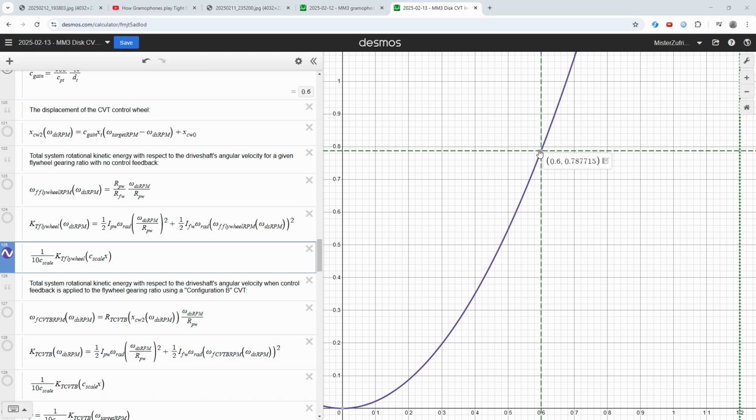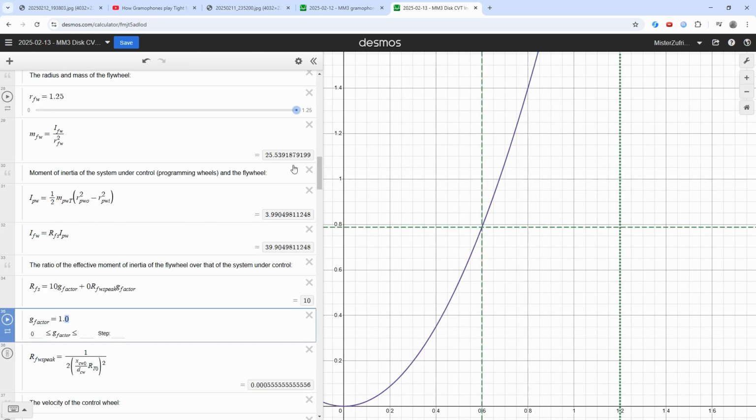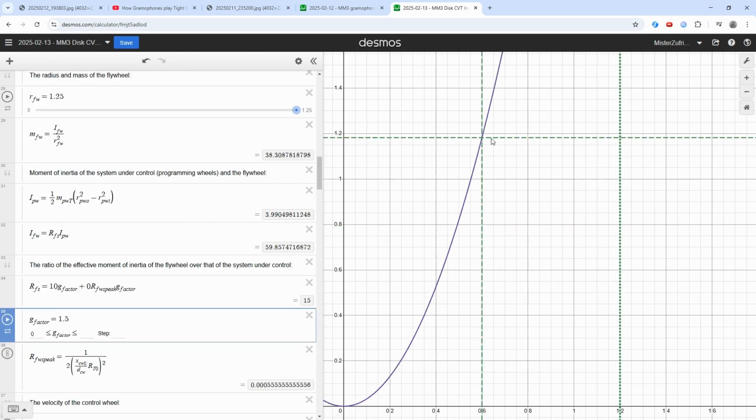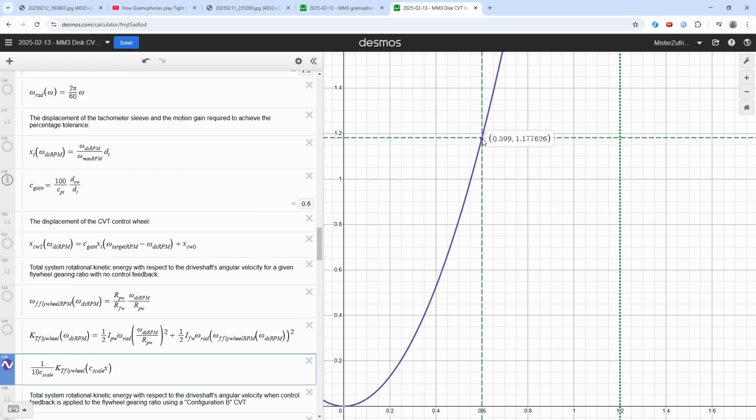So if the machine accumulates an excess of around 100 joules, then that would increase the speed from 60 rpm, as seen on the left of the coordinate, to almost 64 rpm. Likewise, if it were to instead lose 100 joules, then the speed would decrease to around 56 rpm. If you make the flywheel heavier, then the curve will increase more steeply, and the speed for the same change in energy will have changed by less.